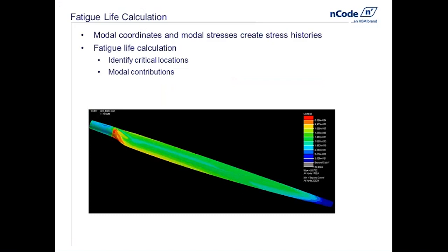What this means is I can go in and, having just a set of measured responses on the structure, I can recompute what the loads had to be coming in, and again, those could be static forces or these modal coordinates.